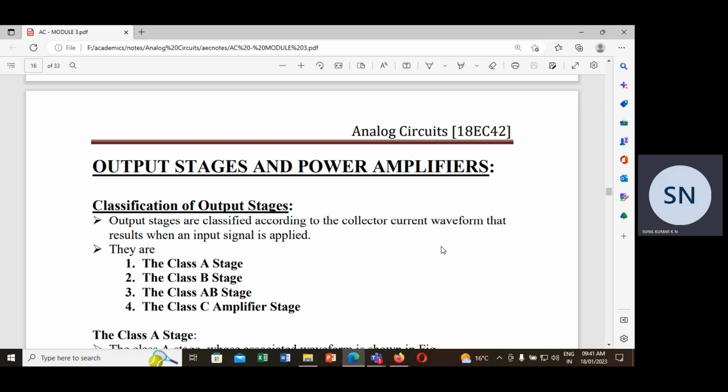There are many intermediate gain stages. It can be common source or common emitter, because common emitter as well as common source are the basic single stage amplifiers which we have analyzed thoroughly. The same thing, when cascaded as I told, will have multiple stages. A single stage alone will not give 10 power 6 gain.